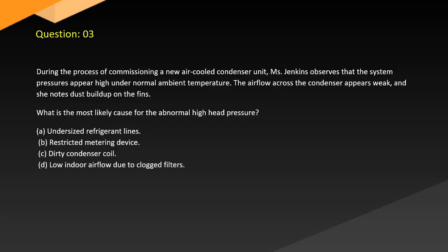A. Undersized refrigerant lines. B. Restricted metering device. C. Dirty condenser coil. D. Low indoor airflow due to clogged filters.